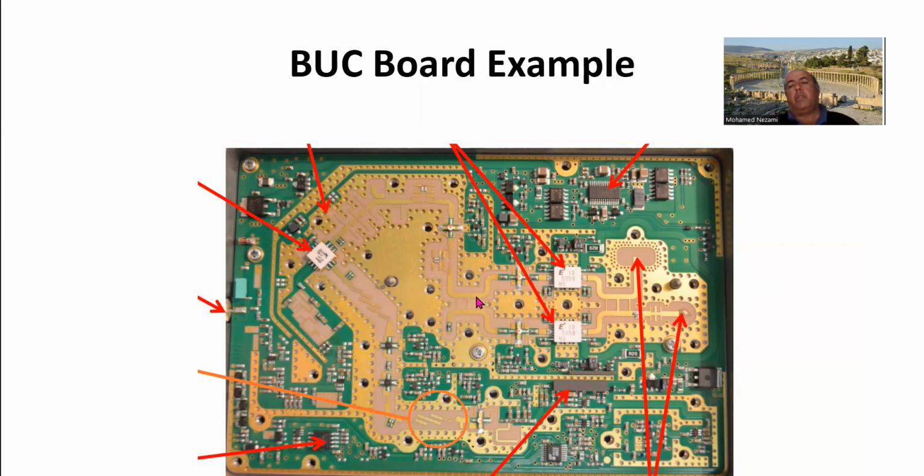Of course, in here, you have to create, in this case, they're sending the signal over two different polarizations. So they split off with a branch line 90-degree hybrid, double for broad bandwidth. So you can see this is the isolated port, 50 ohm. They split off, and then they go through two stages of amplification. Here's a driver, here's the final PA, and then they feed another quadrature here to combine the power from both sides, and then they split the power into two. One goes here and one goes here, okay?